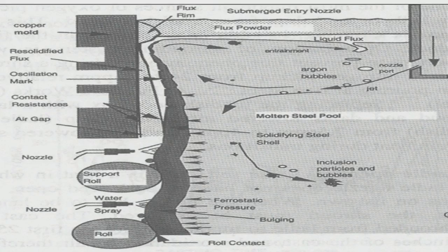Now, after the Tundish, when you are using continuous casting, there is a continuous casting mould. Whether you are casting bloom or billet or slab, whatever it is, there has to be a continuous casting mould. The shape of the mould of course is different depending on what you are casting, but there has to be a mould. What is a mould? The mould is basically, unlike ingot casting, an open mould. You see, this is the mould surface, this is made of copper, this is water cooled copper, this is a copper mould.